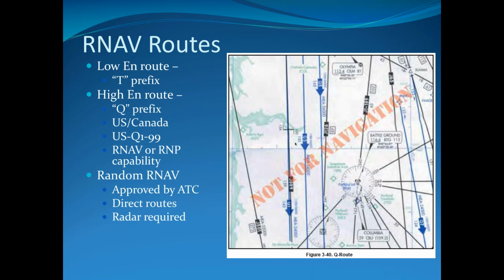So we call these NRS waypoints, and you can actually use those to navigate now, even rather than using these Q or T routes. NRS allows us to really customize and break down a route to what we need to do. It's a lot more accurate. So rather than random waypoints, it is lines of longitude and latitude.